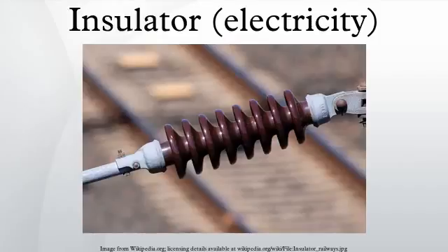Design. The electrical breakdown of an insulator due to excessive voltage can occur in one of two ways. A puncture arc is a breakdown in conduction of the material of the insulator, causing an electric arc through the interior of the insulator. The heat resulting from the arc usually damages the insulator irreparably. Puncture voltage is the voltage across the insulator that causes a puncture arc.